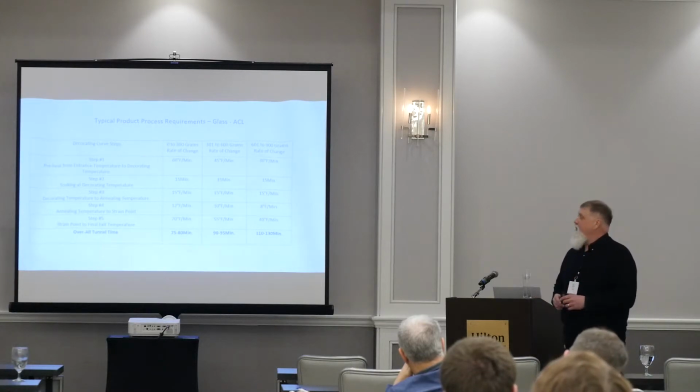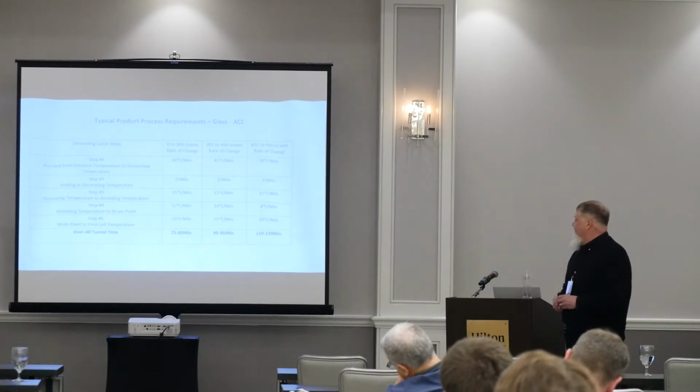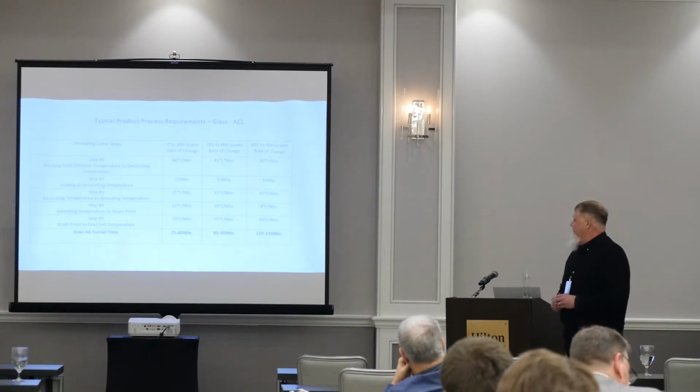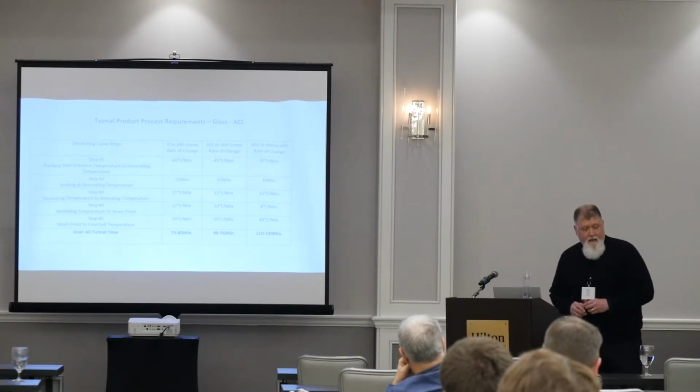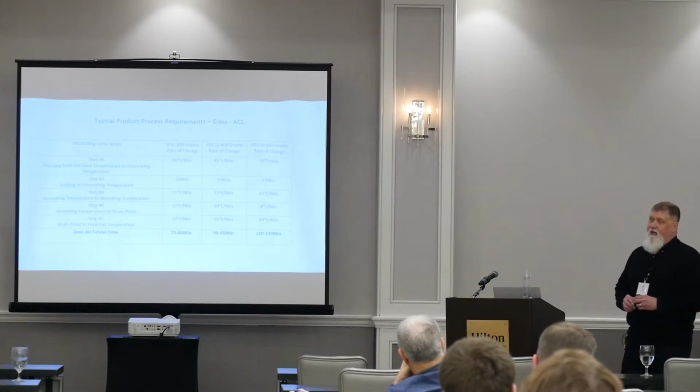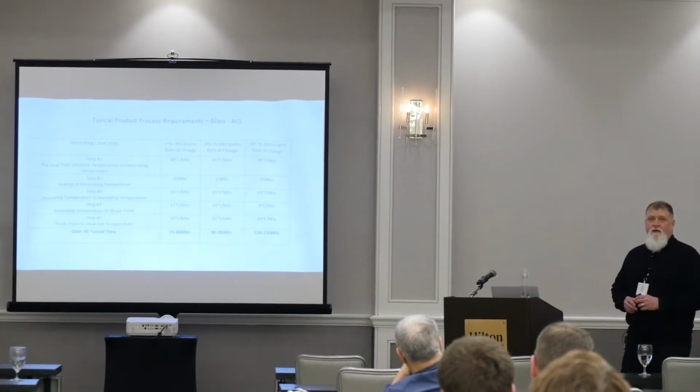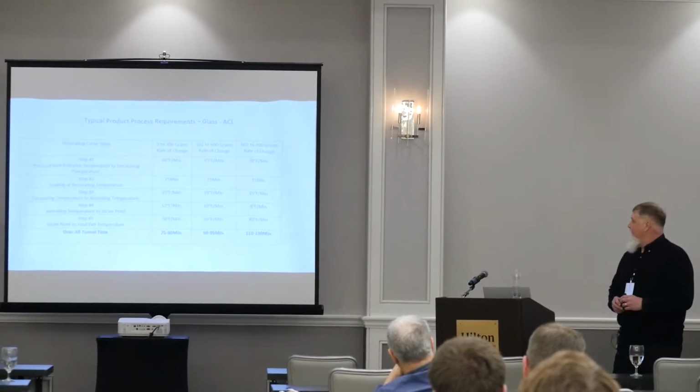So that is something that when you're working with glass, you need to check. I do a lot of that for decorators. They send me glass and I check the annealing on it. Some of you may have your own equipment to do that, a fluoroscope and strain discs, so you can grade the annealing. But I do that for several decorators. If they've got something they're concerned about or in question, they send it to me and I grade it for them.